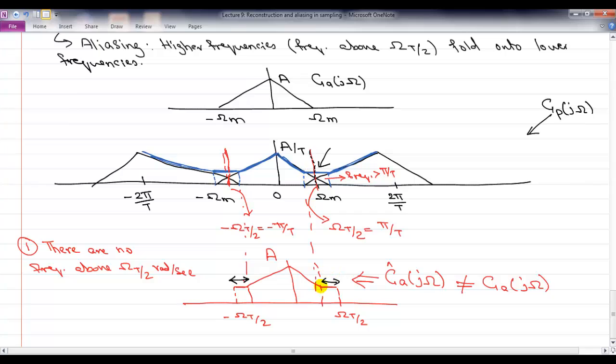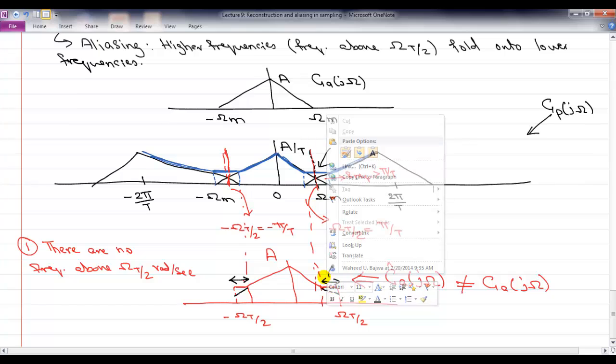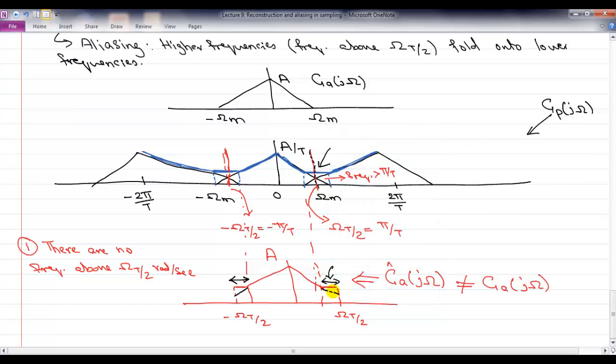So what is happening was that originally your original frequencies were in this region, they looked like this. Okay. But because of the folding, there were some new contributions in this region, and now your new frequencies are basically your old frequencies that were present in that region, plus your higher frequencies got folded into the lower frequencies.